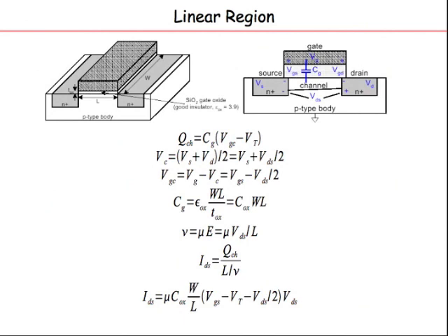Capacitors are okay. There is some dependence on the size, but there's a lot of capacitance which is independent of the size of the transistor. You have to have wires and so on. They're all fixed. As you reduce the size of the transistor, you have less current to charge and discharge, so it takes more time. So you slow down.